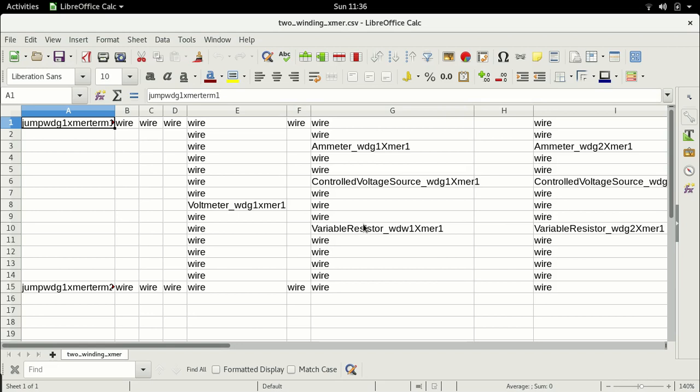If you have a very small resistor, then the current flowing between two voltage sources can drastically change if there are even small changes in one of the voltages, right? Just imagine two voltage sources connected together through a resistance. The smaller this resistance, the more sensitive the circuit. The larger this resistance, the less sensitive the circuit. But then again, you don't want something very large either. If this resistance is very large, it may completely kill any dynamics in this circuit. So we need to choose this a little carefully.